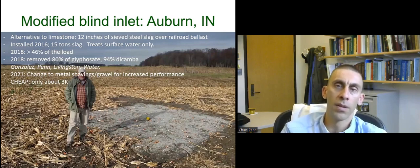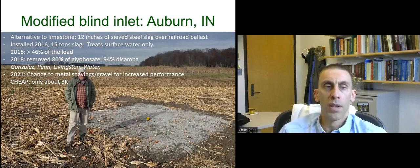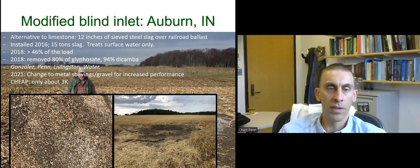And so we've built several of those. The first one we built, we used steel slag at the surface, and it worked pretty good. Built in 2016, by 2018 it removed greater than 46% of the dissolved phosphorus load. It also removed various herbicides as well. So last summer we replaced the media in this blind inlet with a steel shavings gravel mixture. This is what it looks like, your rusty steel shavings, 8% by weight mixed with the gravel. That's what it looks like now. This should remove even more dissolved phosphorus than the steel slag did, and last much longer.